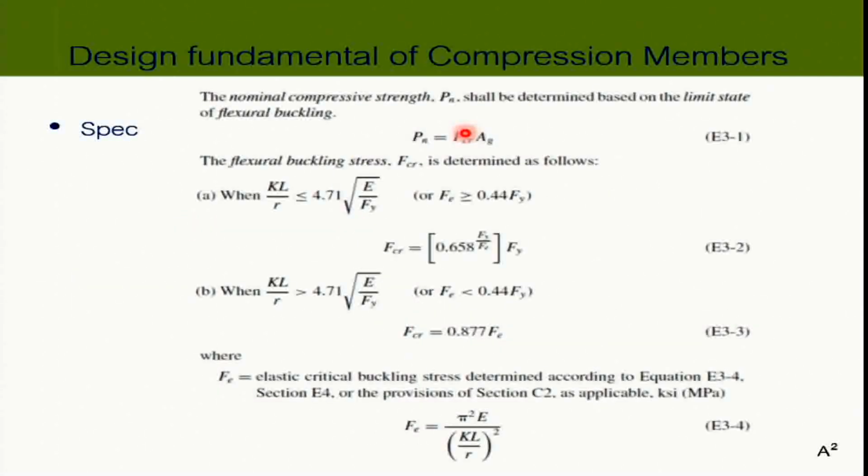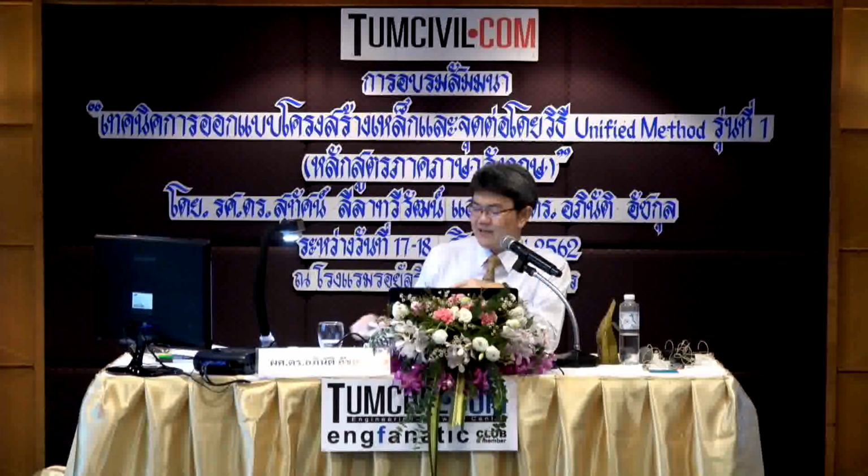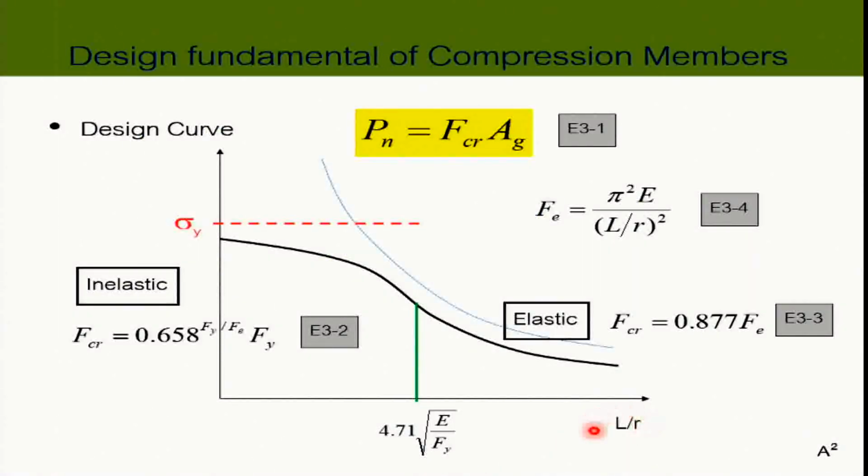One more thing that you need to know is that I believe that most of you here should have an idea about the unbraced length and the slenderness ratio, right? You or you not? Let's talk about that for a minute, okay? Now, this is not the length of the column, you know? This is the unbraced length, the length between brace points, the length where the column is free to move. So, for example,